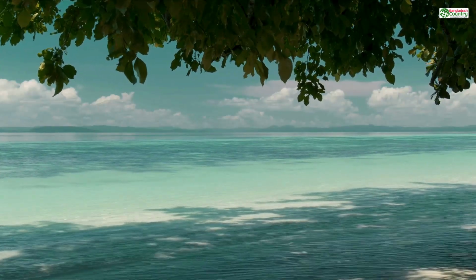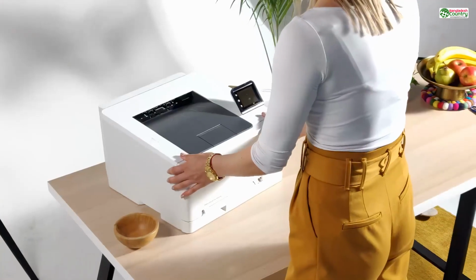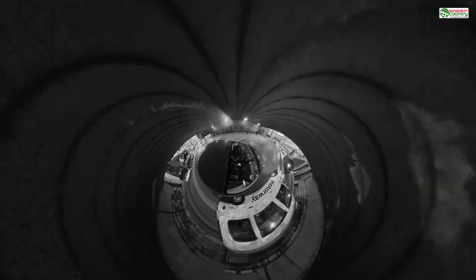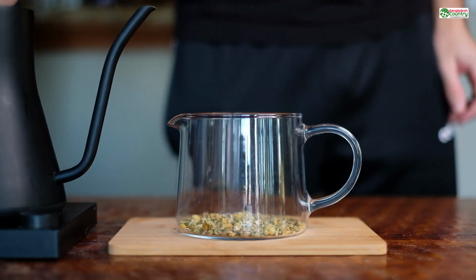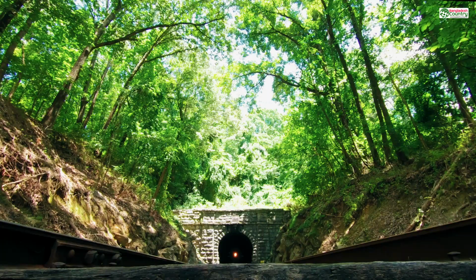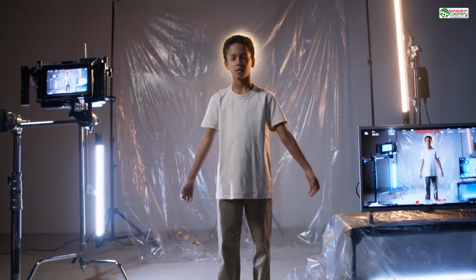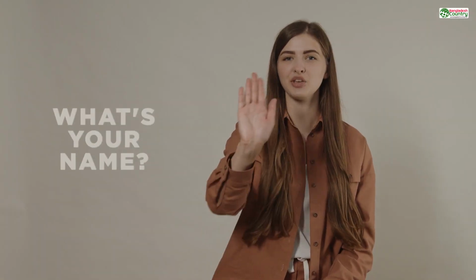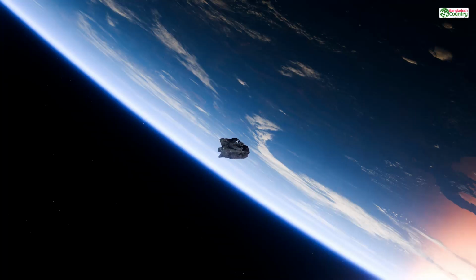Generally, a printer can successfully print overhangs that are at an angle of 45 degrees or less from the vertical. Anything steeper than that, say a flat 90-degree overhang like the underside of a table or the outstretched arms of a figurine, and you're asking the printer to lay down molten plastic onto thin air. And what happens when you do that? Gravity wins. Every time. The plastic will droop, curl, and turn into a mess that looks like spaghetti.